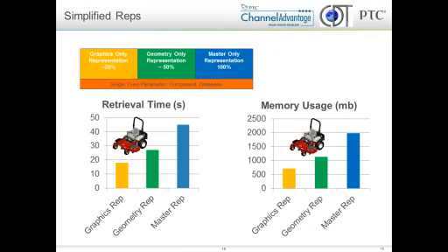What am I giving up to cut the regeneration time down so much? I'm just reducing the level of geometry detail that Creo will generate and show. I don't need to see all of that in the large assembly anyway. Do I need to generate the front left tire so that it's got all of the detail in the master rep when I'm showing a graphics rep? No, probably not. Do I need to be able to read the writing on the tire sidewall when I'm viewing it from a general assembly view? No, probably not. I'm happy giving it simple geometry and speeding up my assembly regeneration.